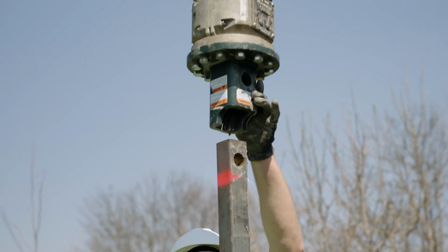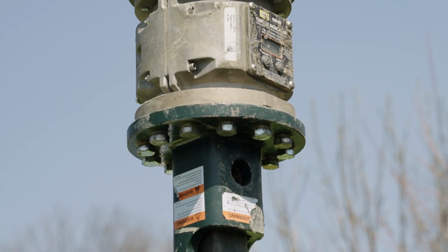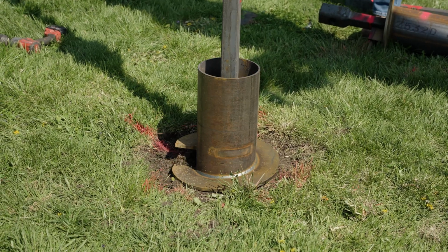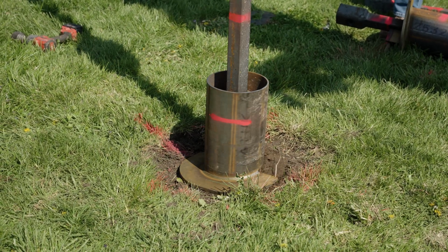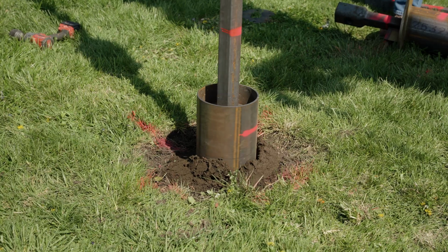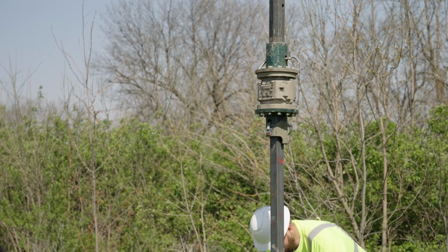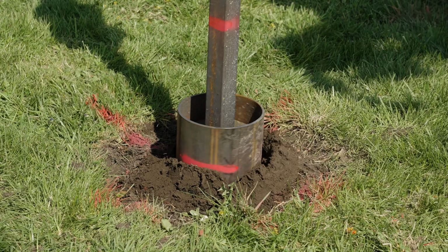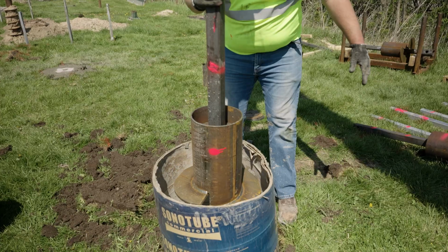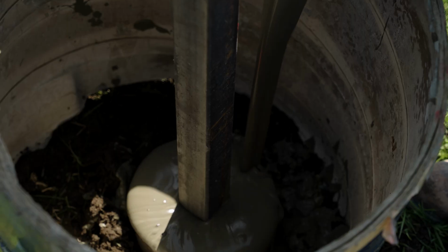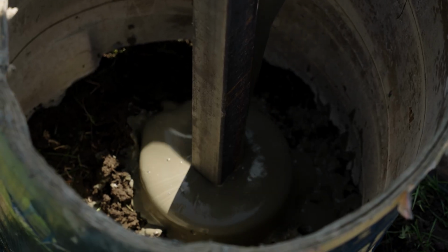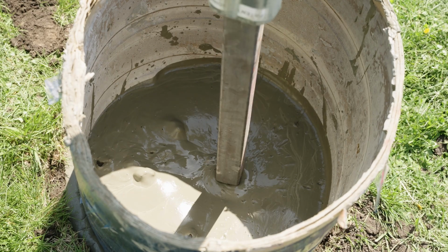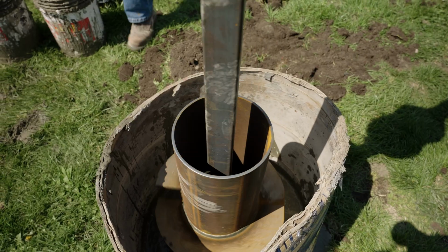After the GroutForce lead section is connected to the tooling string, engage and advance the pile into the soil in a smooth, continuous manner at a rate of 8 to 20 rotations per minute. Apply sufficient down pressure to uniformly advance the GDP sections at 80% to 100% of the helix pitch per revolution. Place the grout in the reservoir prior to advancement of the lead section into the soil. The volume of grout contained in the reservoir must be maintained at a level sufficient to maintain positive hydrostatic pressure